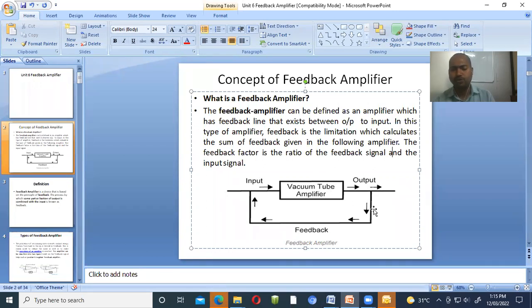See, the definition of positive feedback: the input and the output which is applied back to the input have 0-degree phase shift. Consider the example, we have applied a sine wave, and the output coming is a sine wave. Okay, means they have the same phase. The only change is that if we apply a signal of 1 volt, it gives a signal of 5 volt, right? But without changing the shape. Sine wave is applied, and a sine wave comes across your output. Then that sine wave is again applied to the input, right?